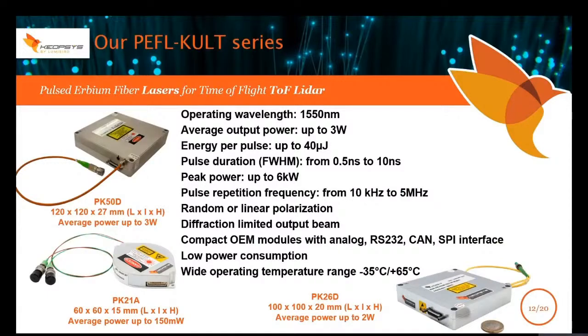For the pulse erbium fiber laser products that can be used in a time-of-flight LiDAR, we can provide a typical operating wavelength of 1550 nanometers at average output power up to 3 watts in pulses of 40 microjoules energy over a large pulse duration from 0.5 nanoseconds to 10 nanoseconds.